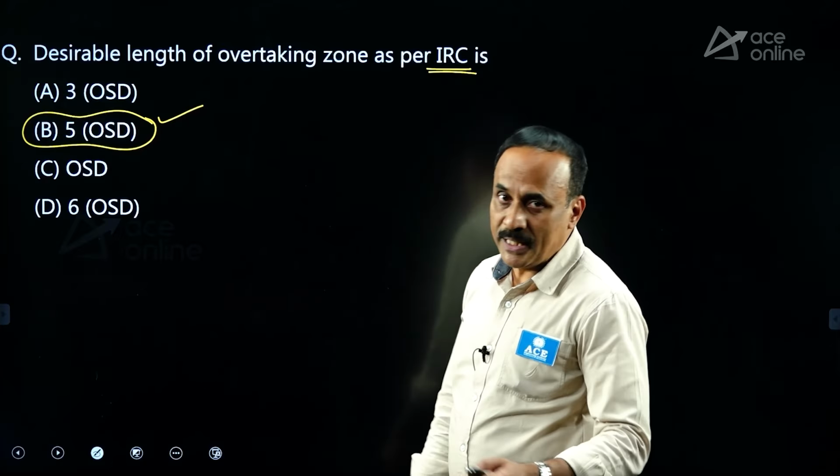The first question over here is, if water is flowing through a pipe of diameter 8 cm under 40 Newton per centimeter square of pressure with a velocity of 3 meter per second, what will be the kinetic head? Now the kinetic head is basically V square by 2g. V is equal to 3, so 3 square divided by 2 times g, where g is 10 according to the question. This has to be equal to 0.45 meter. So answer is 0.45 meter of water, which is option D.